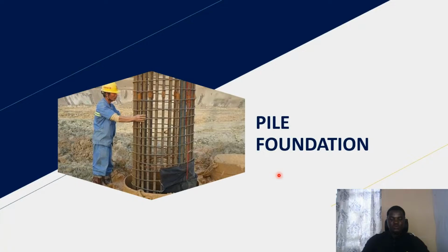So to start with, we want to discuss pile foundation. But generally, in construction, we understand that there are two major types of foundation design. You can either have a shallow foundation, and we also have deep foundation. The definition of shallow and deep depends on the size of the foundation with respect to the depth of that foundation. So when you say a foundation is shallow, that means the depth of the foundation is not as much compared to the other size, let's say the width of that foundation.